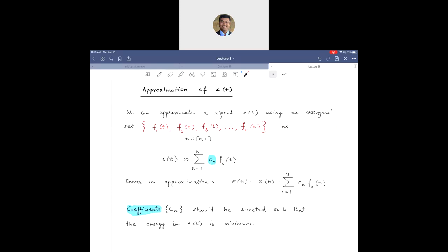You remember I said at the beginning of the lecture, multiple sinusoids getting added up, their amplitudes: if you consider adding up 10 sinusoids, and the first one has an amplitude of 10, the second one has an amplitude of 5, then the coefficient of f1 is 10, the coefficient of f2 is 5, and so on. So the coefficients give you how strong are those projections onto each of those functions fn.